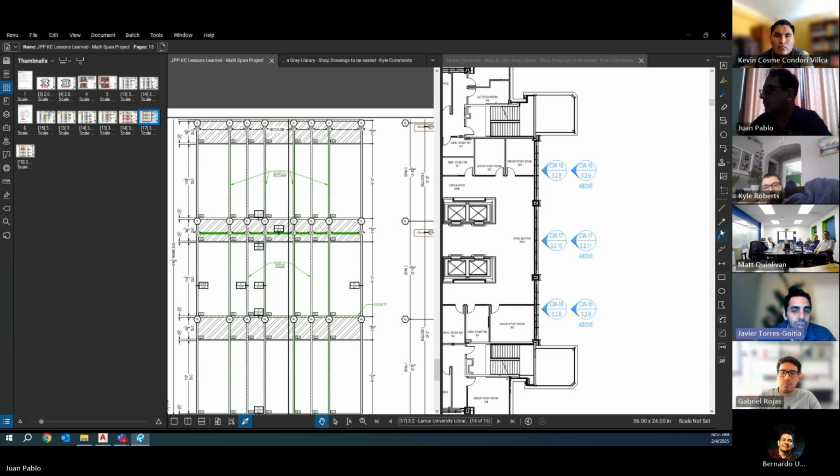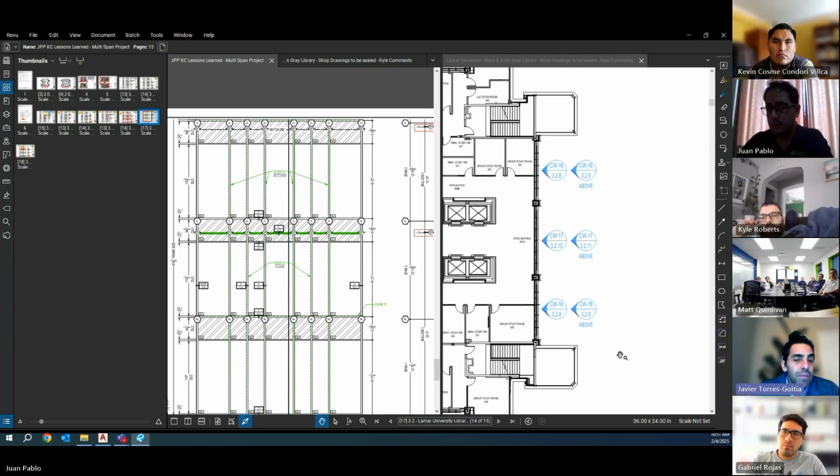So we rationalized, used some engineering judgment, and with the help of Stuart we came up with a reduction of 50%. We landed on 50% by asking how much wind we could actually resist before the deflection on the weak axis becomes an issue. And it came to about 50%.